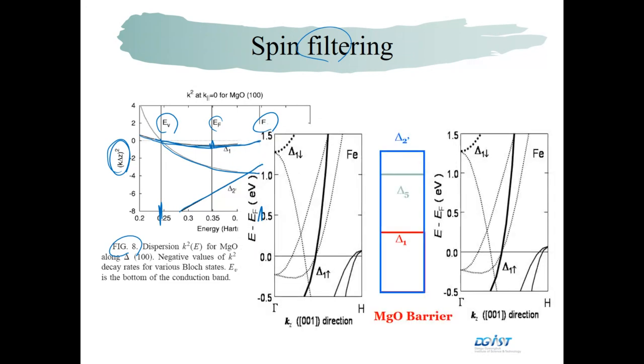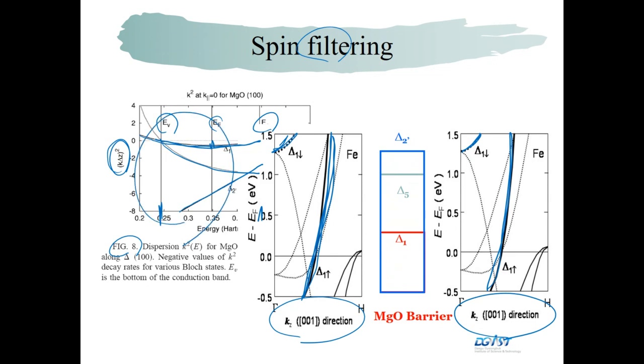So in other words, if you think about this ferromagnetic layer and another ferromagnetic layer, as we said, in a parallel configuration, this delta 1 band can tunnel only into this delta 1 band. And this minus band tunnels into this here. This difference of energy can be easily modeled by the simple barrier model.